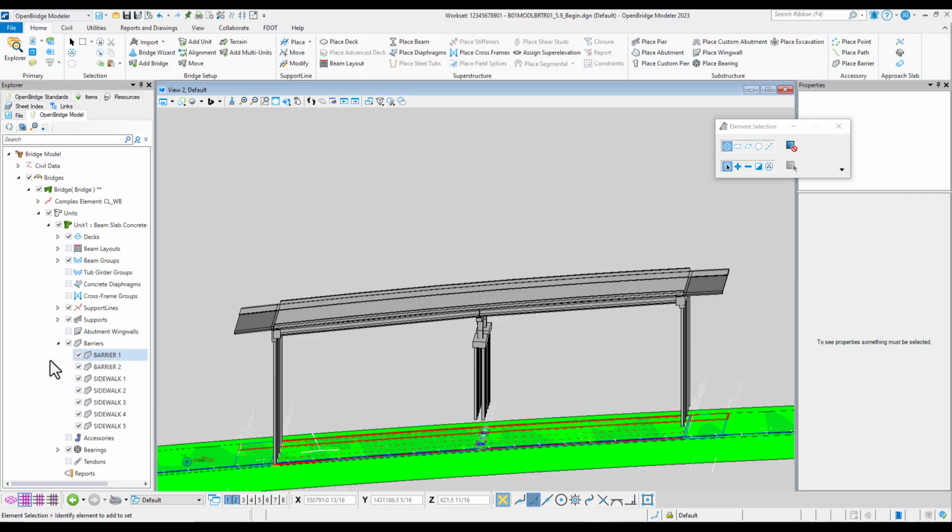This is going to be very similar to exercise 5.5 where we place the barriers on the deck. However, it's a little more involved trying to keep track of which templates need to be used on which portions of the approach slabs. Due to the portions of approach slab with the asphalt overlay, we will have to use different barrier templates at that portion versus the transition portion that will accommodate that extra 1 3/4 inch thickness, similar to the sidewalk templates.